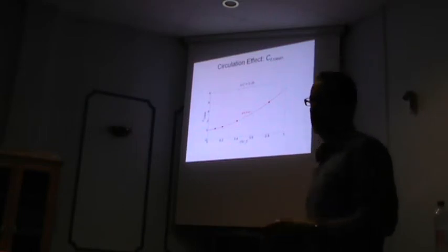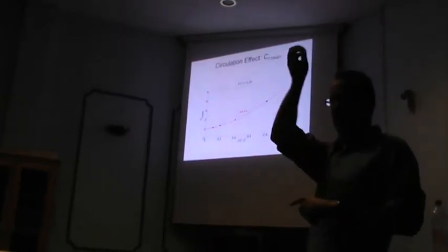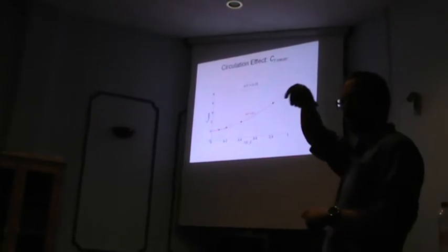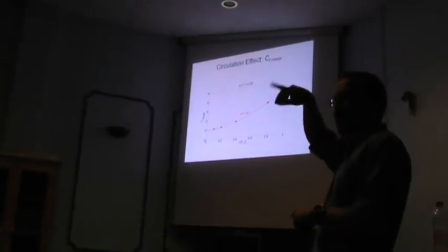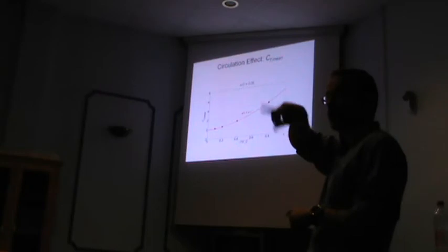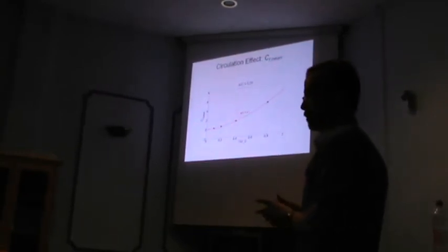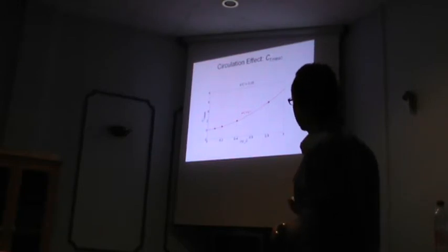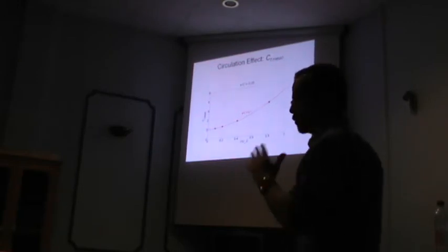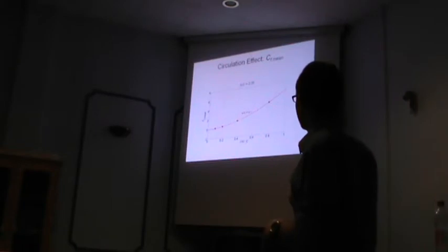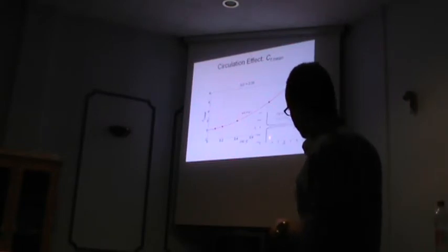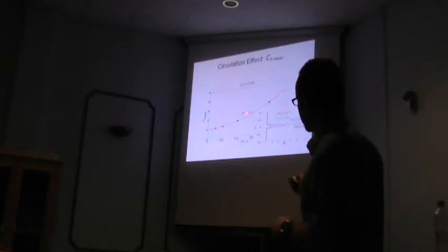This is intuitive because remember, the vortex induces this jet-like profile behind the airfoil, so the stronger the circulation of the vortex, the stronger the jet behind it. So that's intuitive, and I would like you to remember this fact. This is exactly what you see over here. I'm just showing the velocity profiles for each one of these 4 cases that we actually calculated.